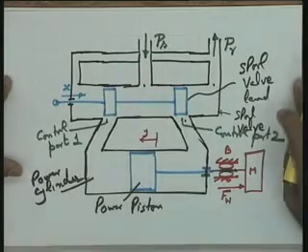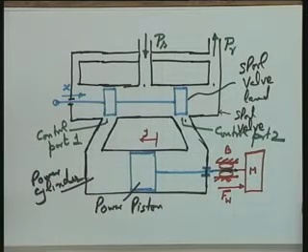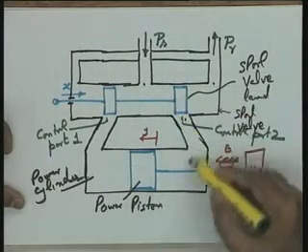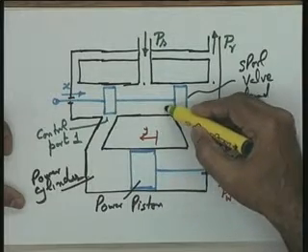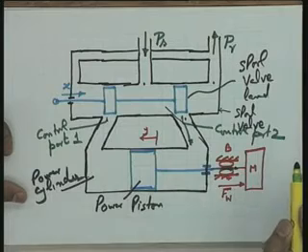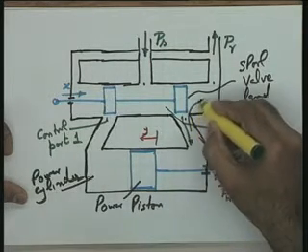Come back to the previous slide which schematically shows the hydraulic motor. Now, you see that in the neutral position you want x equal to 0 and y equal to 0. Help me, how can we achieve this objective with an underlapped valve? Because an underlapped valve will allow movement of the fluid, because this is open, a certain opening having been left because of manufacturing tolerance or by design, and similarly this is also possible.